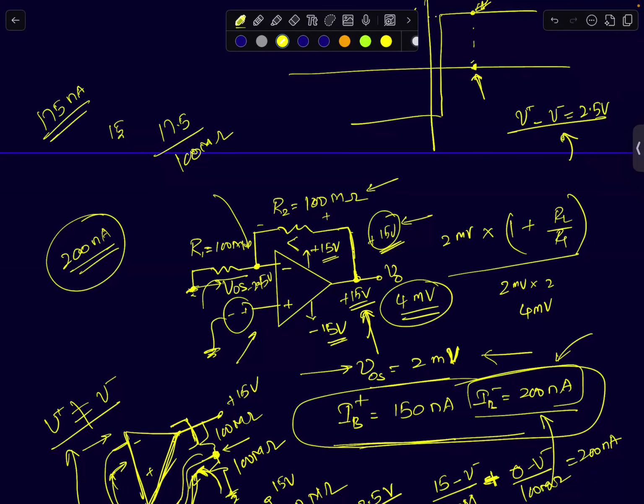So there is another question. In that case, some current is coming from the ground, but that is actually V in that we have considered as ground. So basically the extra current is supplied by V in. Exactly. I've assumed zero source resistance, so you can assume most of the current is coming from the input itself.